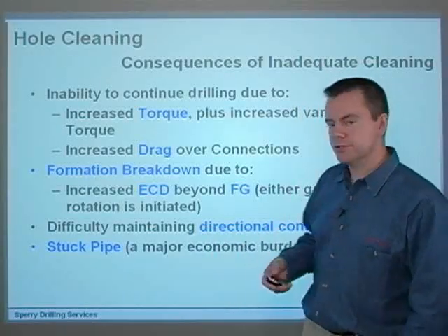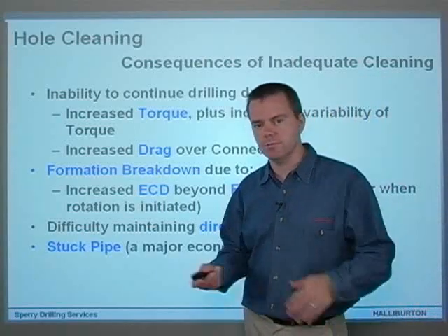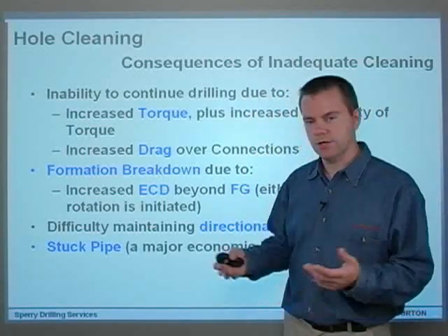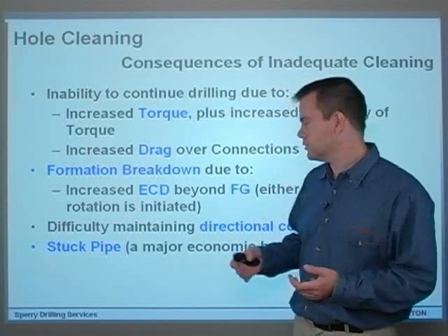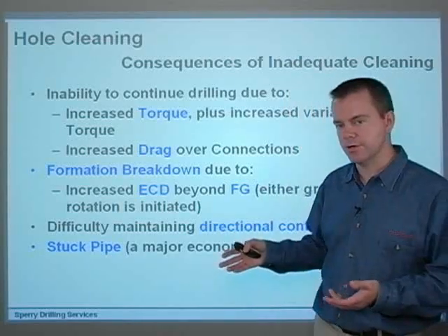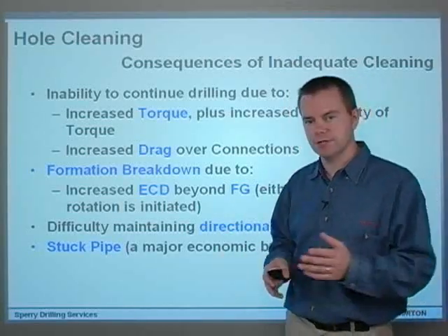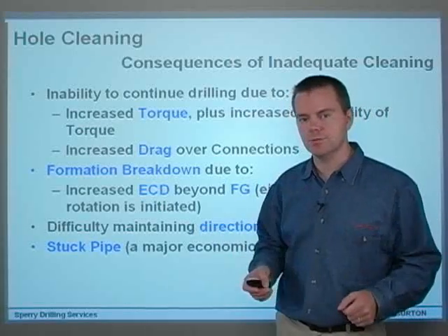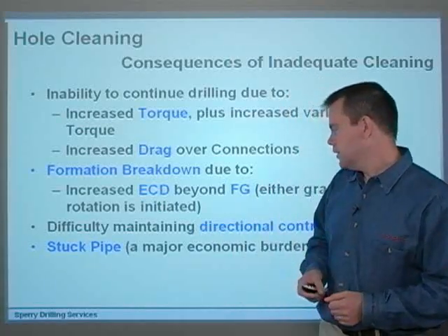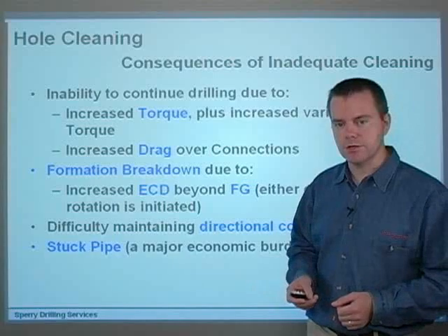You'll have difficulty maintaining directional control with a motor or with adjustable gauge stabilizers or with GeoPilot. If you're not cleaning the wellbore correctly, you'll have difficulty actually moving the pipe in the direction you want to go. And in the end, you'll end up with stuck pipe.